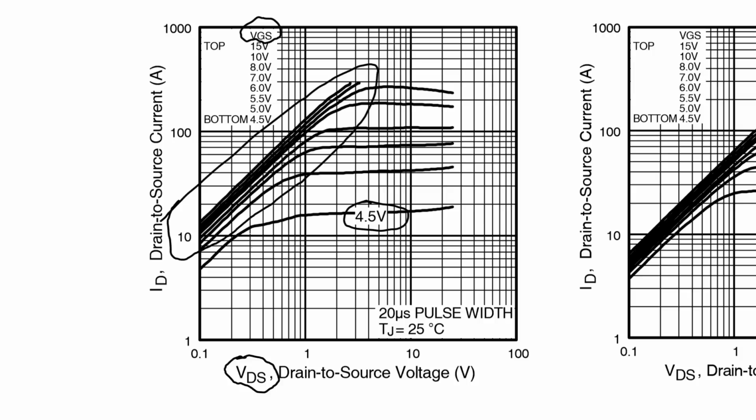And you can see that what happens is it won't pass very much current because the current is over here on this axis, right? So the maximum current it's going to flow is not that much, but you are going to get a rather large voltage, and that's what we saw when we were driving it at the threshold. So if that's not what you want, which is typically not what you want, right? You want the switch to be on. You don't want a large voltage drop across your switch.